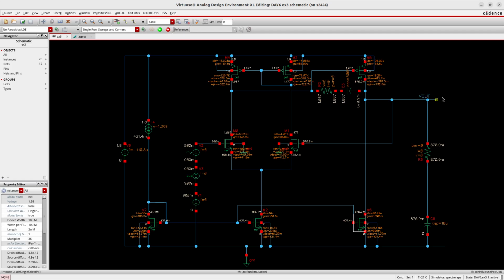I mean, if we have capacitive loads, those capacitive loads will also require current at high frequency, so we have to calculate the impedance at the highest frequency of interest and then dimension the current that is needed to drive that impedance in parallel to the resistors that we have, etc. So in this particular case, this capacitor is just a short circuit because it is connected in series, but if it had been in parallel, then we would have needed to calculate the impedance of that parallel capacitor in parallel to the resistor to find the right current that is needed.